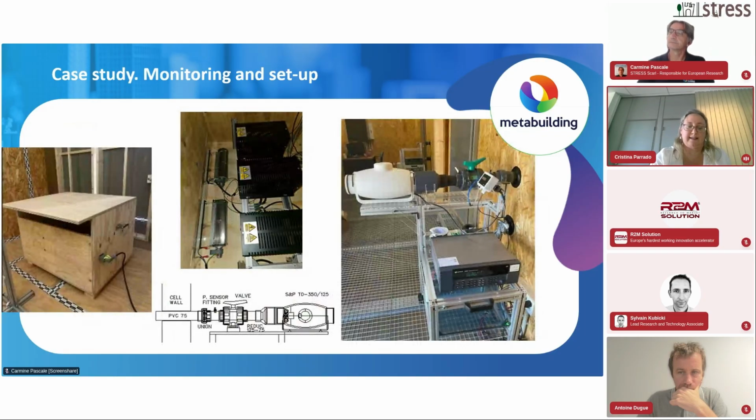We decided, as I said, as a consortium and with the partners, that we had this heating system that consists of 3 resistors of 400 watts and 2 fans that circulate the hot air from the inside of this box, which is mounted into the cell. In addition, we have this airtightness system for the test. We do the airtightness test once before we test and after the test to see if everything is working properly. And the monitoring system is mounted outside the cell. So just in the cell, we have the sensors and the element that we are going to test. Next one, please.